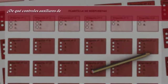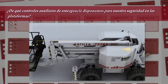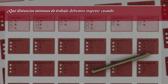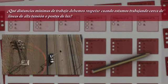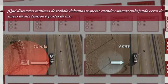What auxiliary controls do we have at our disposal for our safety on the platforms? The red emergency stop button and the manual pump for lowering in case of a breakdown. What minimum work distances must we respect when we are working close to the high voltage line or light poles? The minimum distance that we will keep from a high voltage line will be about 15 metres and about 9 metres on lines located over wooden poles.